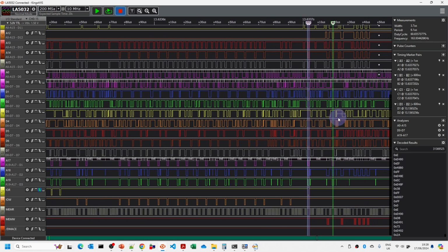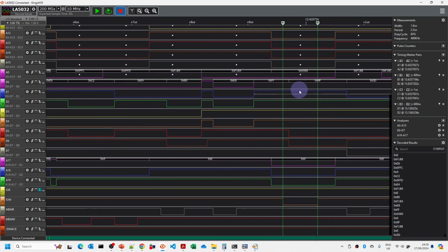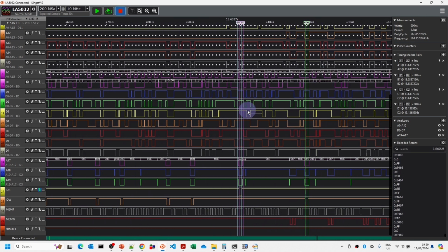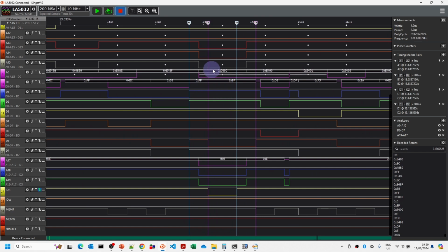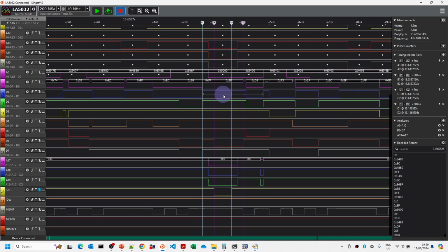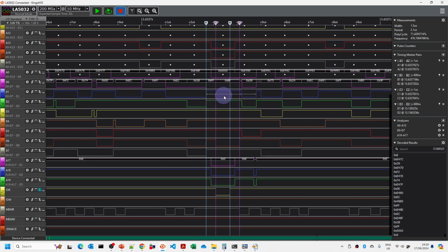And if we go along to the right here, we can see that port 80 is the power-on self-test port. We get 9F being sent out there. So this looks to show us that something's not quite right going on here. And this is just reading and writing to the registers in the DMA controller. And if we can't read and write to these registers reliably, then the chances of everything else working reliably is remote.